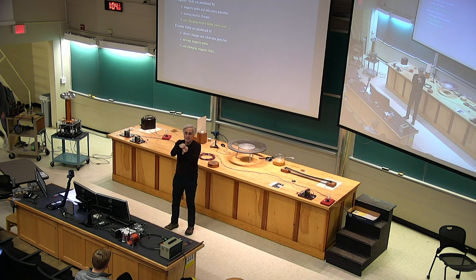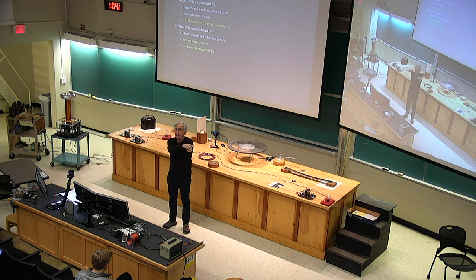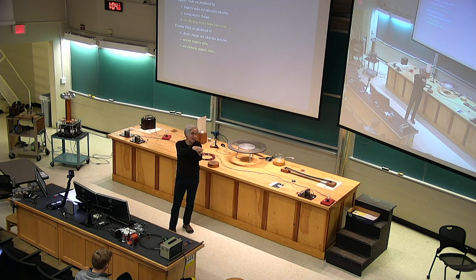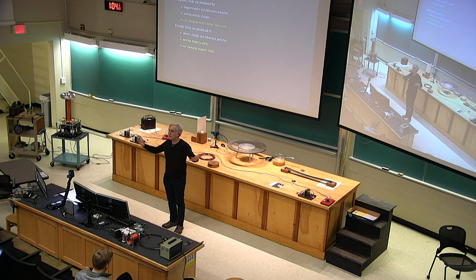The electric field between the two wires is changing with time. There's an electric field, after all, whenever there's a gradient in voltage. And there is a gradient in voltage. You've got 100 volts here on the power wire at this moment in time, and 0 at the neutral wire. And a little while later, this is different in voltage. So between the two, there's a gradient in voltage. So therefore, there's an electric field. And that electric field is changing with time. You follow that idea so far?